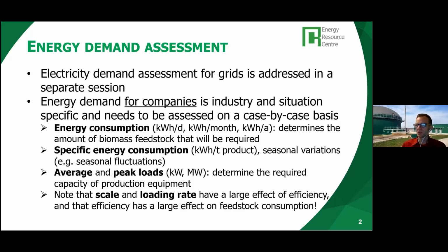What is important, of course, secondly, is the expected load, the average and peak loads in kilowatts or megawatts, because that will eventually determine the required capacity of the energy production equipment. All the installations will need to meet the required loads.